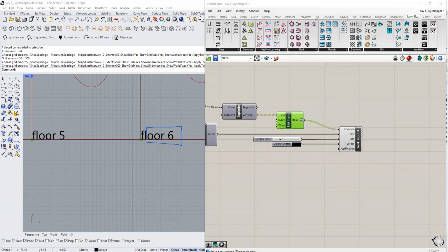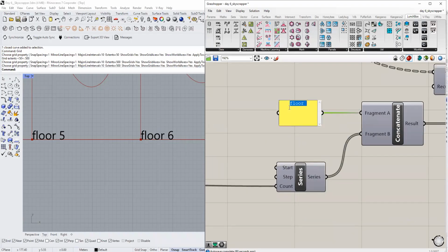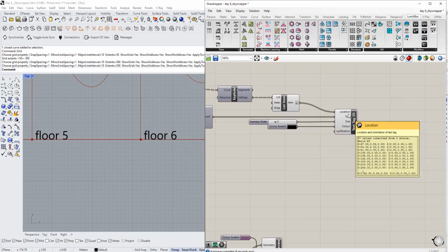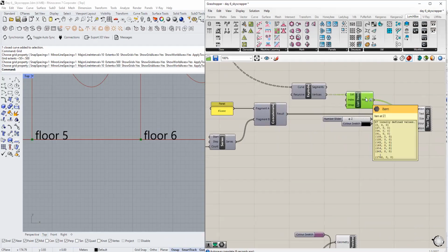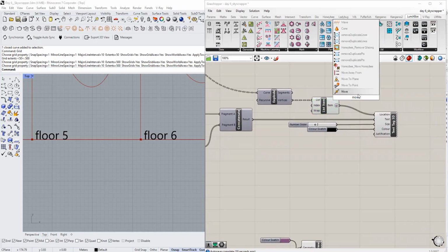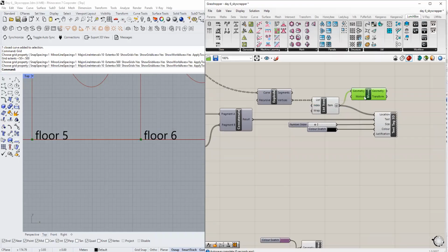But just put enter, like in that text. Actually, yes, that is a smart suggestion. I wasn't thinking of that. I was thinking of something else. What I was thinking is you change the location. Instead of having the location at the vertex directly, you can maybe move it a bit using the move component. And move it along the X vector.